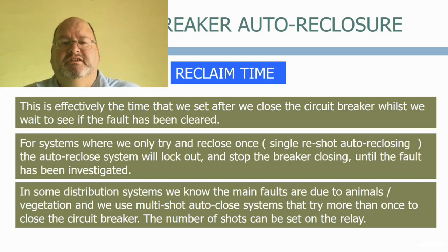Balanced with this is the need to protect the integrity of the equipment. Repeatedly closing equipment onto a fault may cause permanent damage to the equipment and will certainly lead to increased maintenance times further down the line. So we need to quickly identify the difference between a permanent and a transient fault.